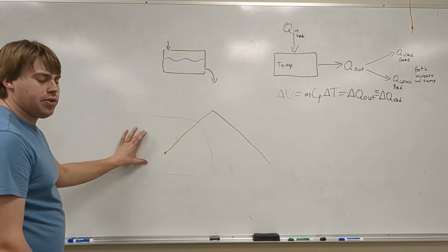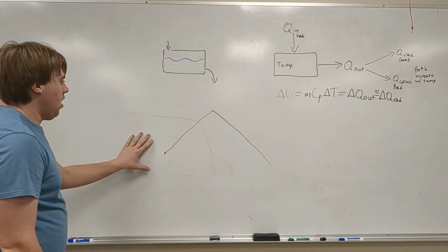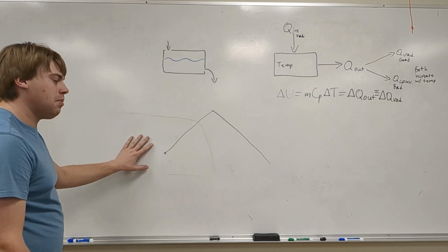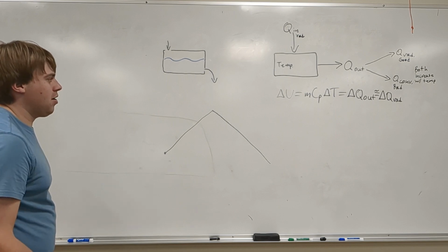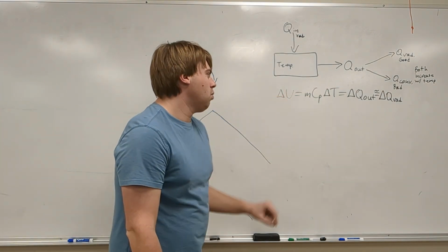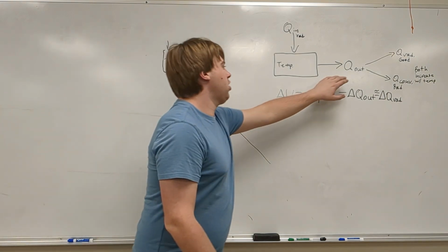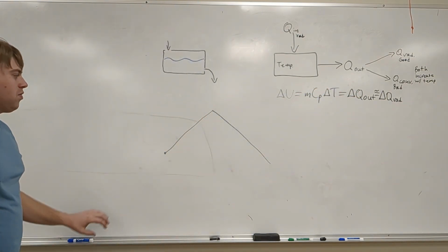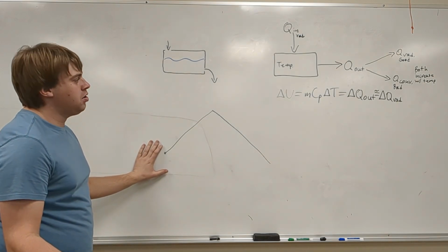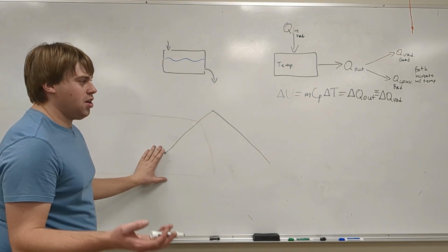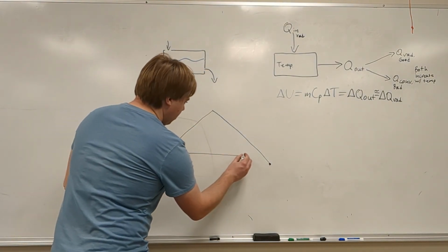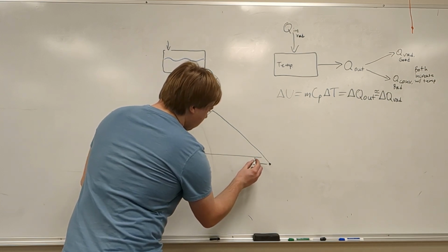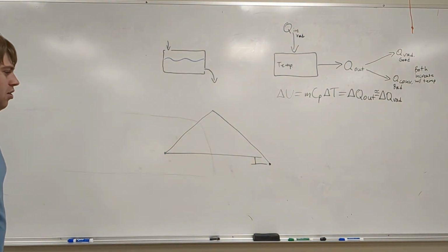Now the test did end at a lower temperature than it started, and that's okay because it happened for both pieces. To determine which one lost the total amount of energy to radiation, whichever one lost more radiation, or Q out, overall, would have to be the winner here, since we decided any change in Q out was change in Q radiation. So looking at the two endpoints here, and the difference between the two, we can figure out the overall loss of energy.